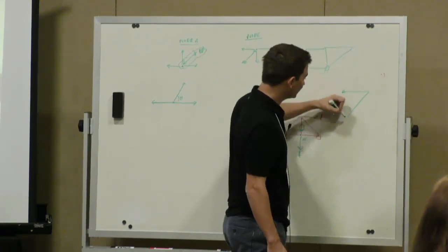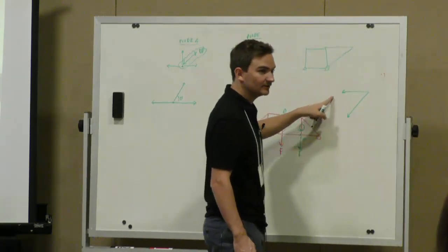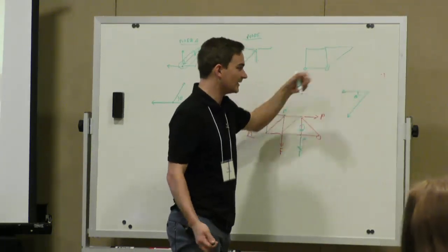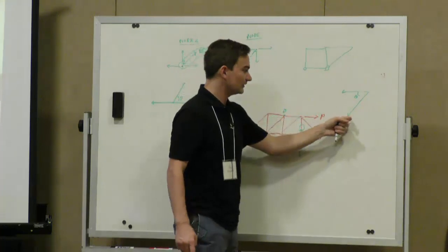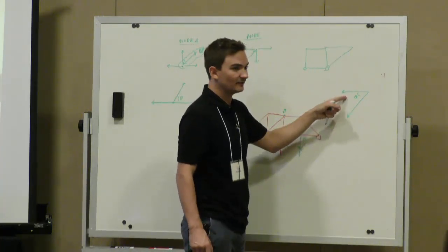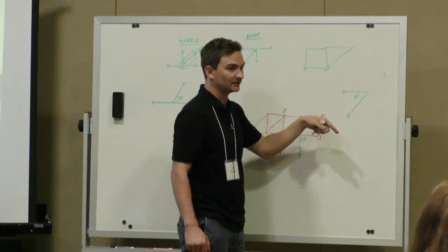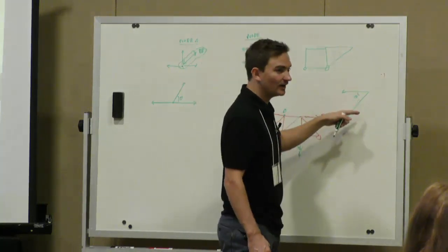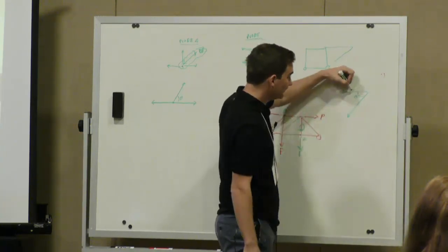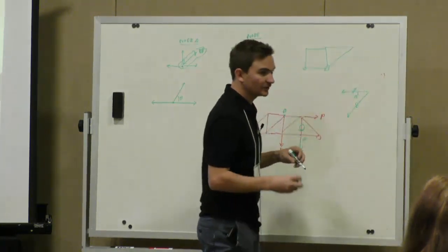This can only be in the x direction. This is in the x and y direction, and they're acting at some angle theta. So this has a y reaction, but this one does not, so it can't react in the y direction. If you were to sum the forces in the y, you would only have this component. Therefore, both of these would be zero force members.